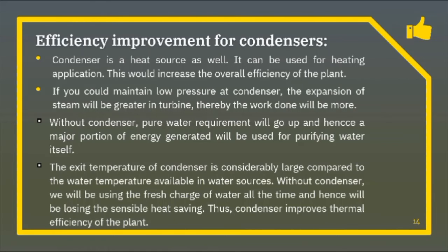The exit temperature of the condenser is considerably large compared to the water temperature available in water sources. Without a condenser, we would be using a fresh charge of water all the time and hence would be losing the sensible heat saving. Thus, the condenser improves the thermal efficiency of the plant.